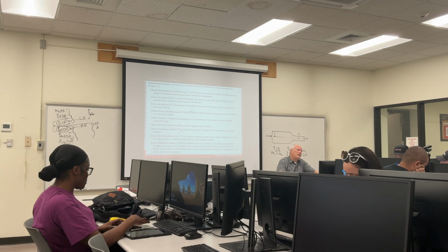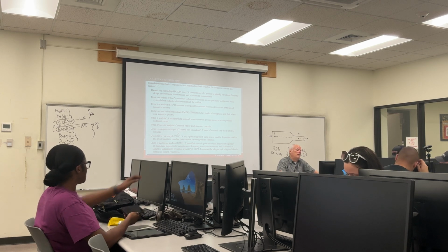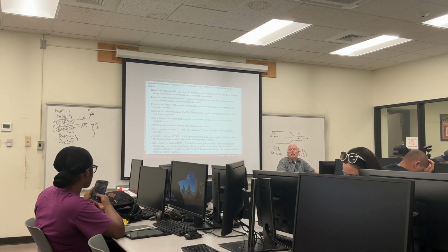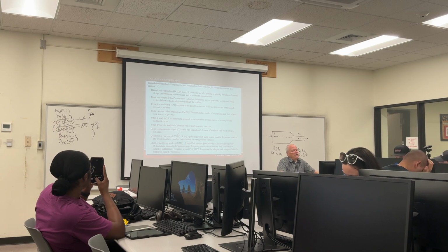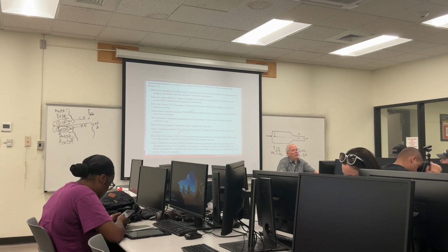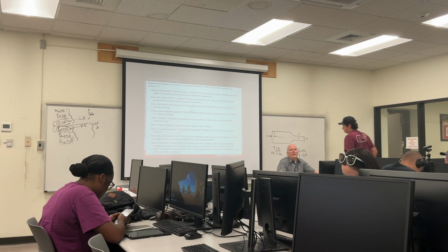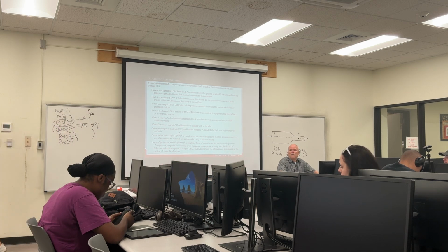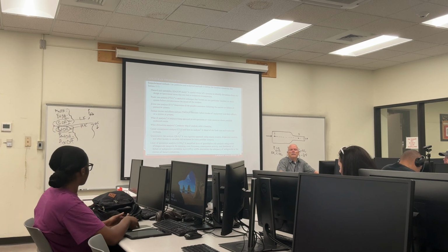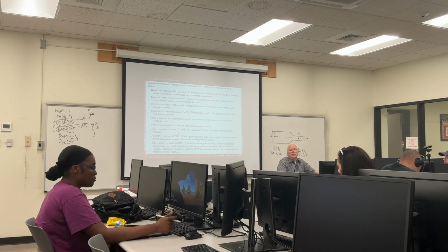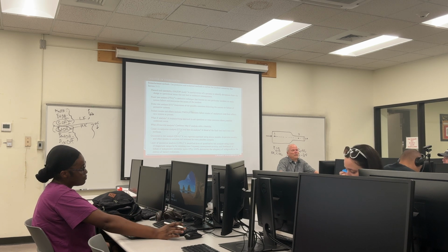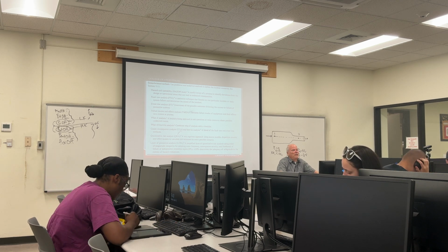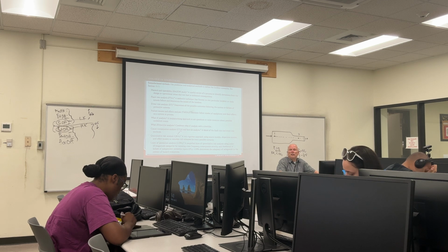Then there's a bow tie, which is kind of a blend between fault tree and event tree. And then quantitative risk analysis is used. It is really a method to try to calculate the probability and the risk. But the problem with it for our industry is that it's just too complicated to do that analysis for an actual chemical plant. So that would be the ultimate, but you just can't do it.